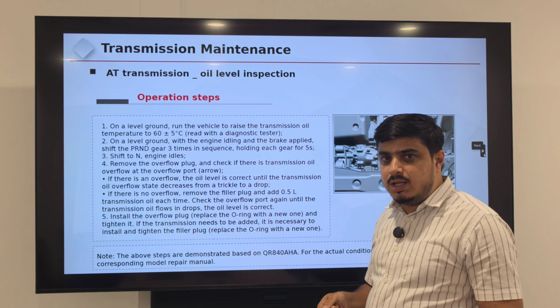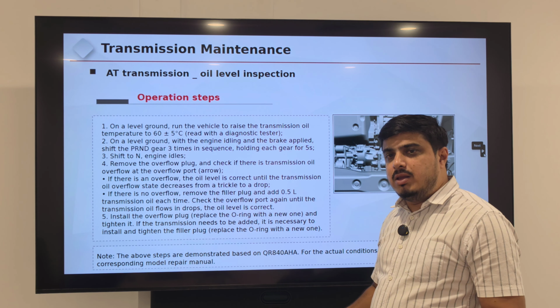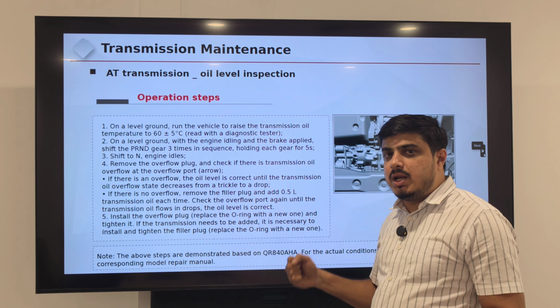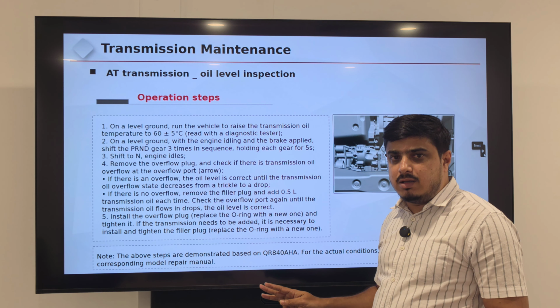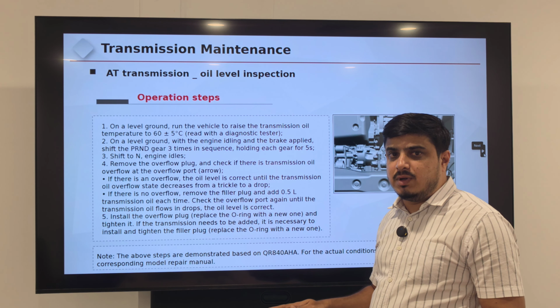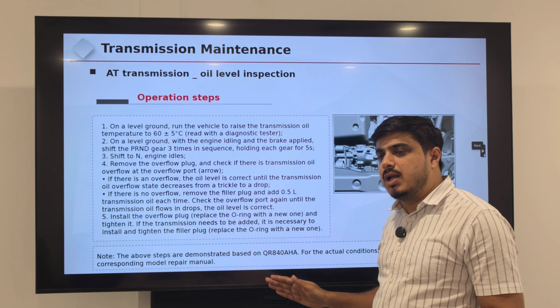Press the brake pedal, then shift the gear lever P, R, D in the same sequence, 3 cycles. For every shift of gear, stay 5 seconds.